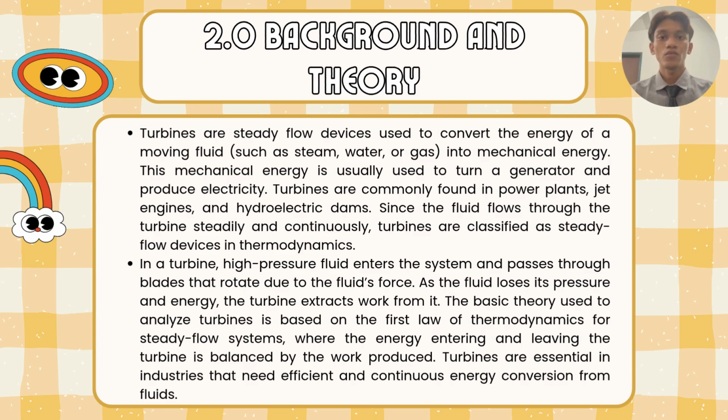Next we go to 2.0, which is background and theory. Turbines are machines that convert the energy of a moving fluid like steam, water, or gas into mechanical energy, which is often used to generate electricity. They are steady flow devices, meaning the fluid flows through them continuously. As high pressure fluid enters the turbine and passes over its blades, the blades spin, producing useful work.